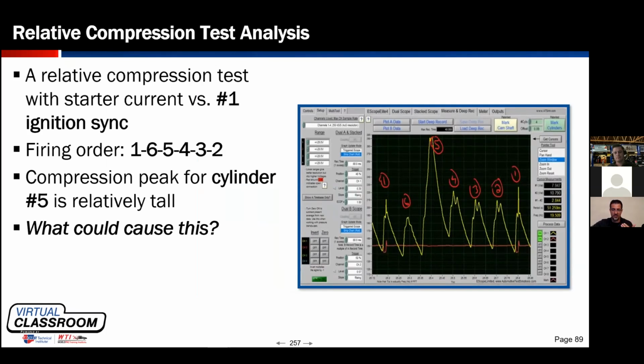As soon as the exhaust valve opened and we pushed that oil or that coolant out the exhaust port, if I was filling a cylinder fast enough that the next cycle experienced the same thing, we'd have some symptoms leading up to this, right? We'd have steam coming out the exhaust. We'd probably have coolant dripping out the tailpipe. And certainly we'd have a dead miss at all times. It didn't just happen instantaneously. So oil or coolant filling the cylinder, like a hydrolock situation, is probably unlikely.